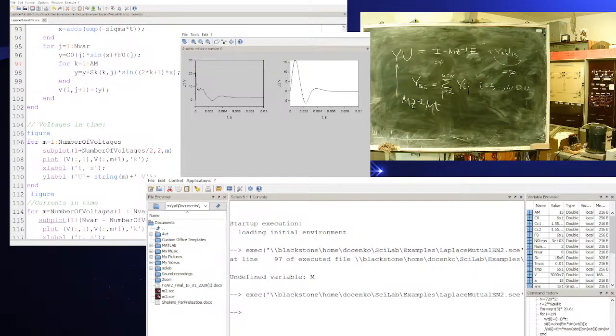I'll need to switch. Yeah, these voltages are calculated. See some oscillation in it. We use numerical approximation. Here is the calculated primary voltage, here is the calculated secondary voltage. 15 volts, decay in 6 milliseconds.